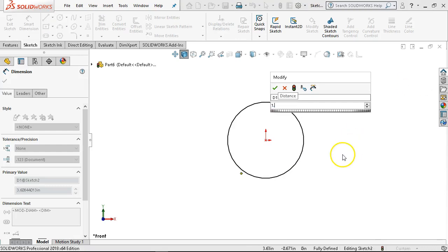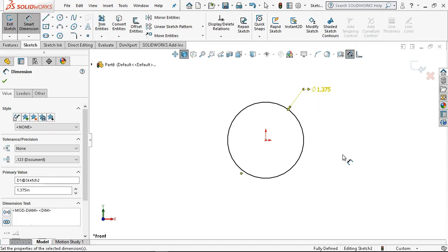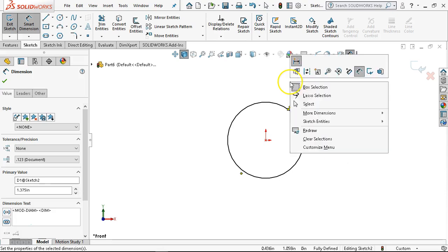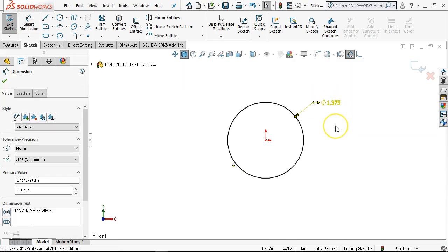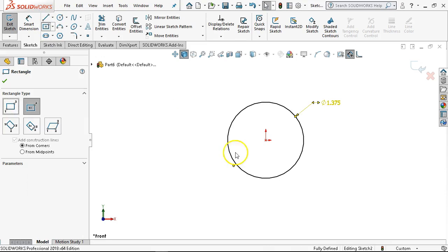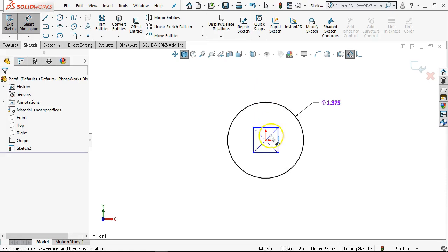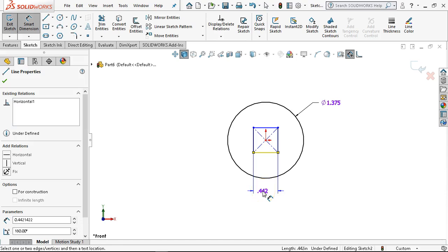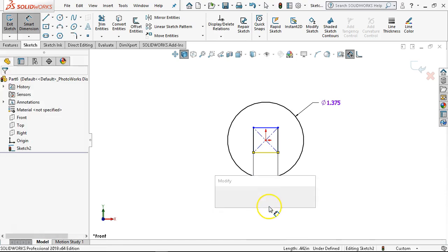Again, whenever you see those 2 place decimals, you should be asking yourself, should I carry it to 3, 4, 5? You know, even though we don't have the precision at the 2 decimal places, when I take this into the drawing, if I decide it's 1.38, I can always let it round. All right, and then the rectangular square in the center will give me 0.5 by 0.5. Nope, 0.5 by 0.31.